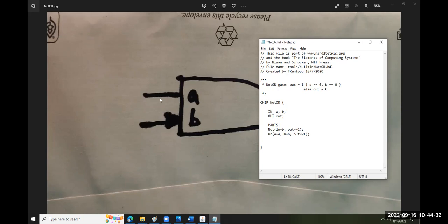So if I were to take this and explode the view, I'd have the B input pin, I'd have the not, and then coming out of the front of the not would be a W1, and then the W1 goes into the B of the or, right? So the A of the main chip feeds into the A of the internal or. This is really clean, right?